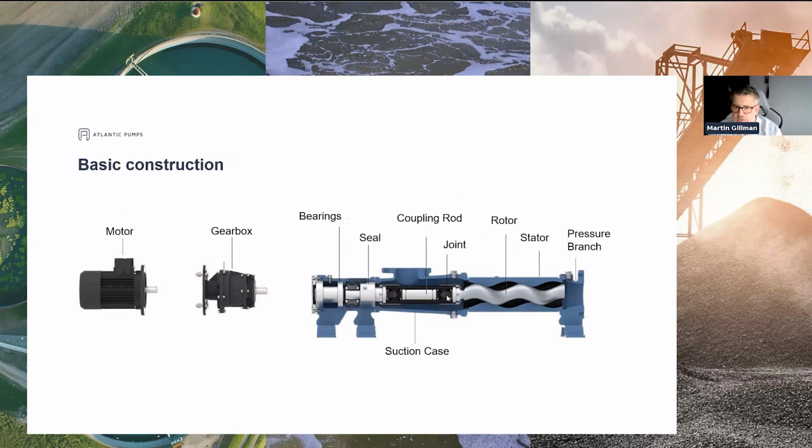In this particular case, we're using a carbon universal joint, but you can also use pin type universal joints for lighter duty. And in some cases, you can use a flexible shaft, which is a long, thin whip type shaft between the two. It makes the pump a lot longer, but it relies on that torsion, on that whip, rather than actually having physical universal joints, okay? And then, of course, you've just got your main casing parts here, which will be flanged for the pump.